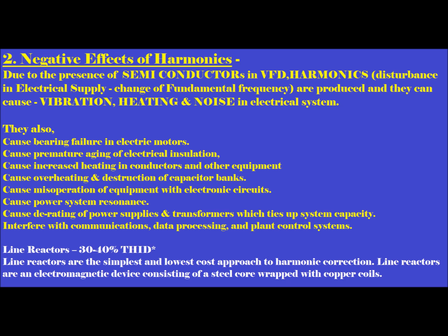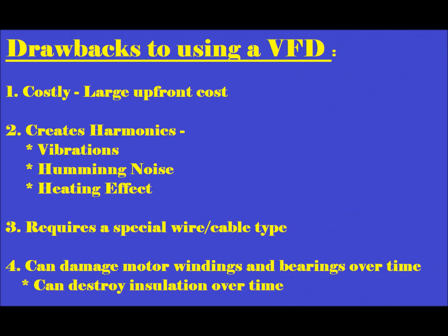We'll come to the third point now. The third and fourth points are basically extensions of the second point. Since harmonics are being created in a VFD, we need a special wire or cable. Special in the sense that we have to provide extra insulation so that even if aging or heating affects the cable, it will continue for a longer period of time. These special or higher insulation cables are not required in the case of DOL or soft starter. So that is the third point.